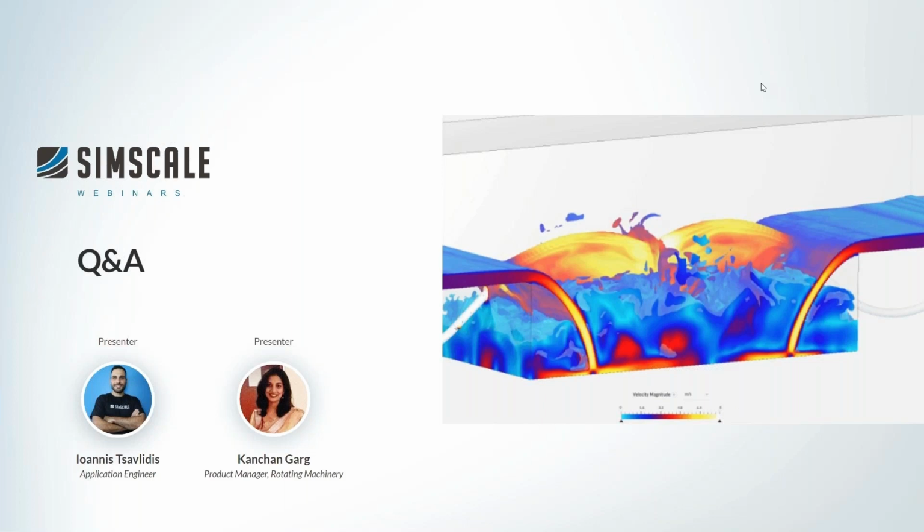Can you simply download the mesh generated by SimScale? No, you cannot, and then use it in another CAE package. For our open-source based solvers, we do give the option of downloading the results and mesh, which can then usually be analyzed in ParaView. For this proprietary solver, we don't yet have the option, but we are working on it, because a lot of times users want to download results and mesh, as you mentioned, to be used with other tools, and sometimes simply for archiving purposes. So that's a feature that is often requested, and in future we will try to integrate that as well.